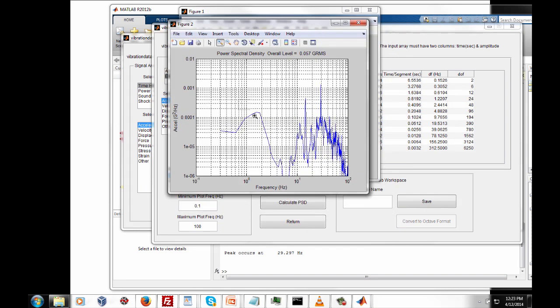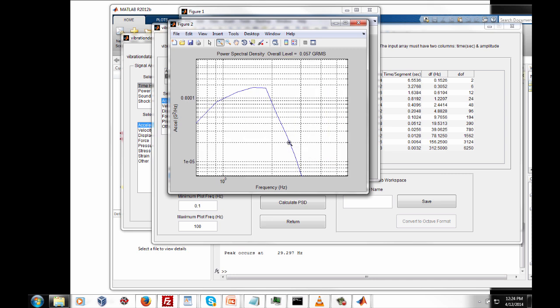There's something we can do in MATLAB. I'll show you what this is. First of all, I'm going to identify the spectral peak there. I've got 1.52, that's frequency in hertz, and then you can see the corresponding amplitude there. That's a g² per hertz amplitude. Now the next thing I want to do is calculate what are called the half power points. That's -3 dB, so that's going to be 1/2 the g² per hertz level.